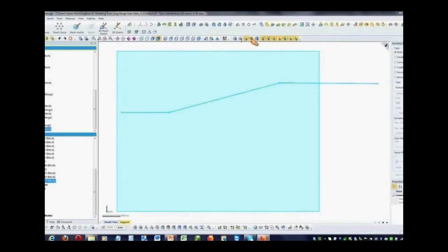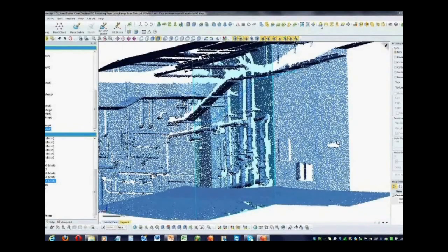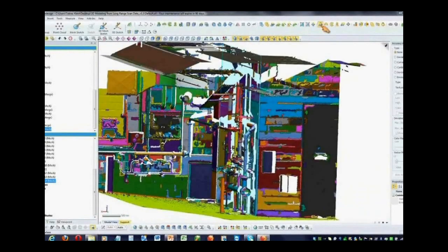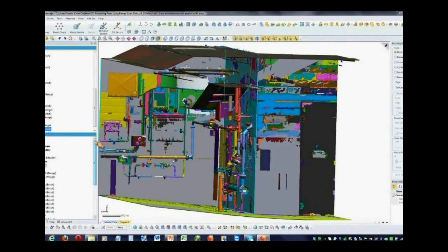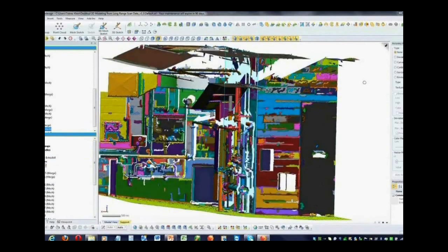Okay, and then I can show my mesh again. And then I can use extrude. For example, in this case, I'm extruding a surface. And then here it is. And now I have a second surface. Now I will hide the first surface.